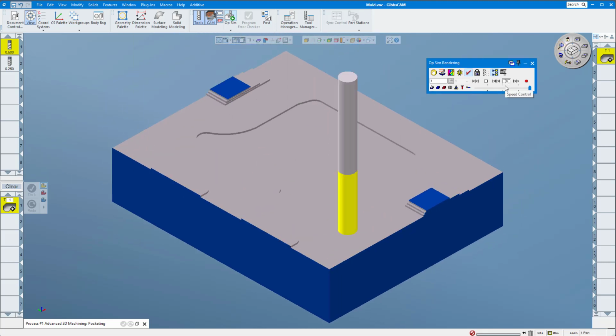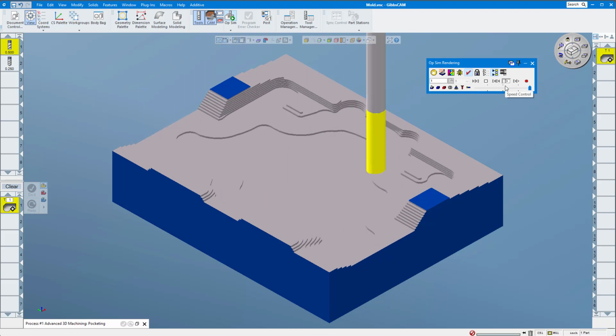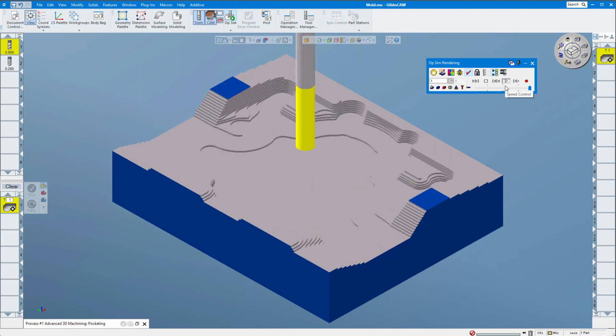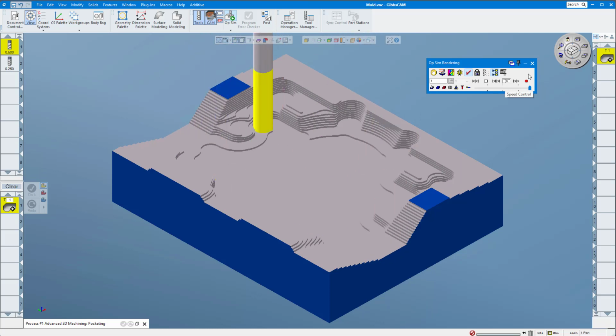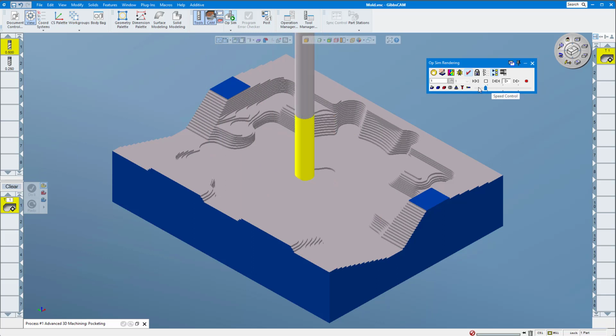So this is great, right? We have that small step over, which is going to really take that pressure off that quarter-inch ball. The problem is your machine never runs this fast, right? We're looking at something like, I don't know, depending on the machine you have, geez, that might even be fast. But the machining time is really going to take a long time. So you either put a lot of pressure on the tool, or you machine out with very small steps to take that pressure off.